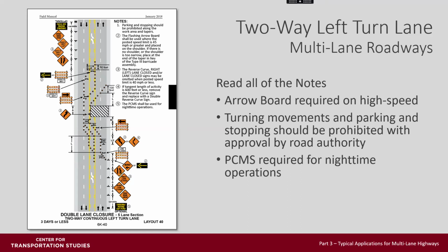Parking and stopping should be prohibited in this area, which sometimes requires advance signing of the parking and stopping if there's parking in that area. And you have to coordinate that with the local road authority and law enforcement.